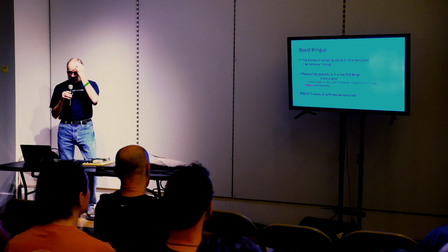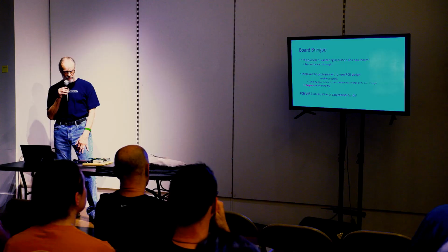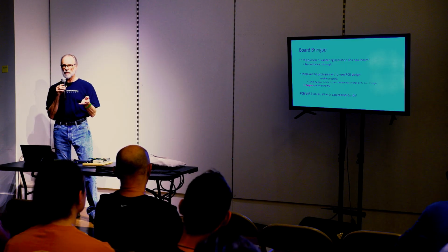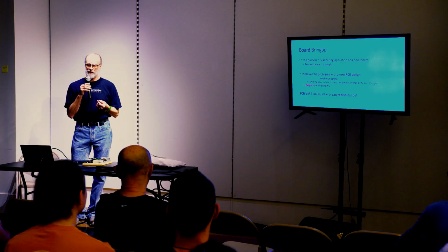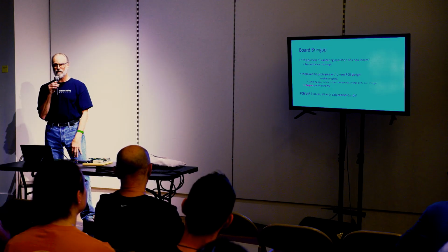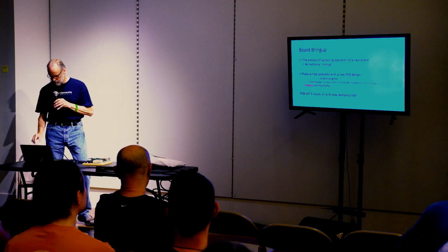So in this case, I had 5 issues, all had easy workarounds. The most serious issue was that my debugger was absolutely dead. I could not put software onto the board. That was very problematic. And it turned out that I had the silk screen, the pins, labeled wrong. So that was an example of an extremely easy workaround.